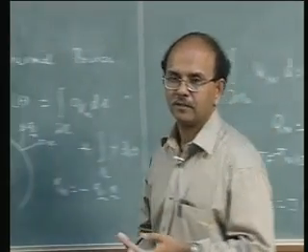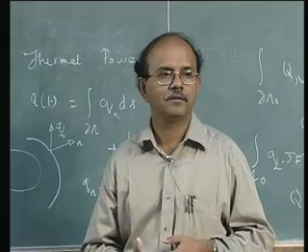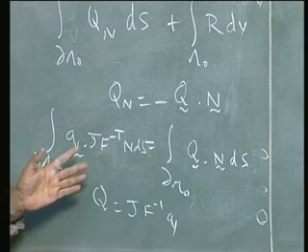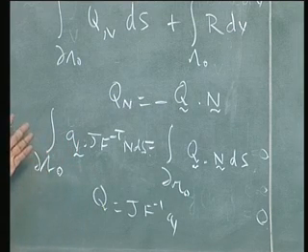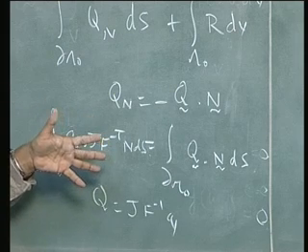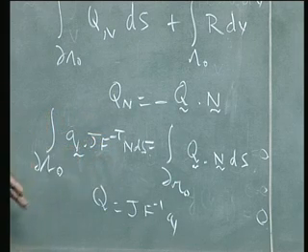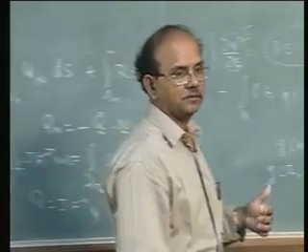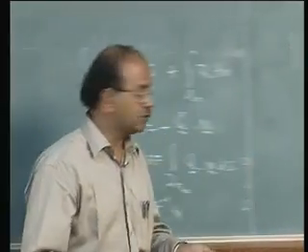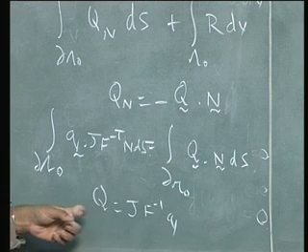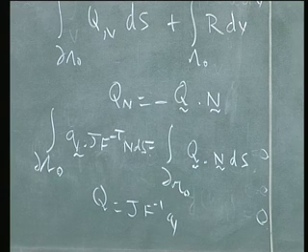From the Cauchy stress, sigma dot n d small s, you got P dot N d capital S. And what was that? It is the first Piola-Kirchhoff stress. So people call this Q the Cauchy heat flux and this the Piola heat flux.